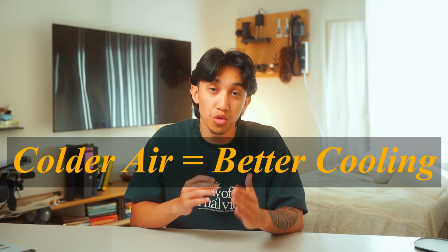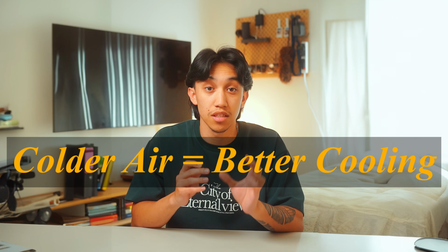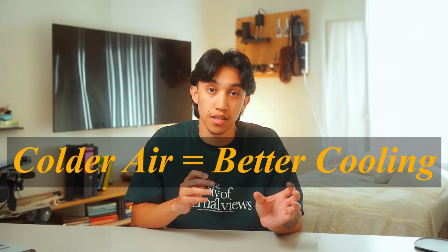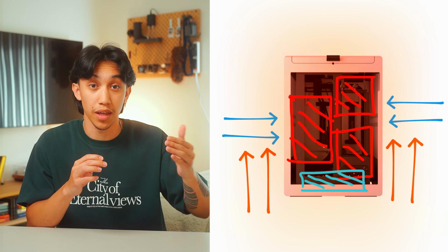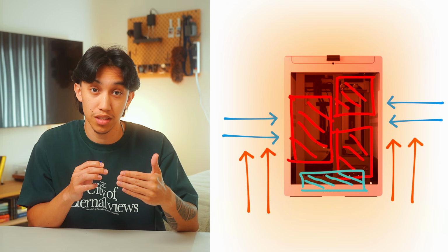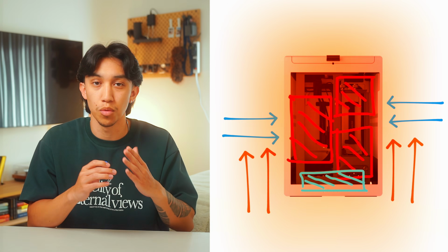Simply put, the colder the air coming in, the more ability it has to take heat away from those heat sinks. So if you have hot air being exhausted out the bottom and eventually rising up the sides to become the air that's supposed to be cooling your components, you're gonna end up with an endless heat cycle that'll almost never stabilize in temperature. But what if you change your CPU cooler fans from intake to exhaust? Will that fix the problem? No. It's kind of the same issue.